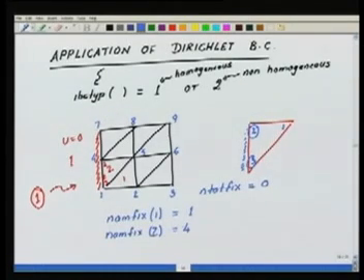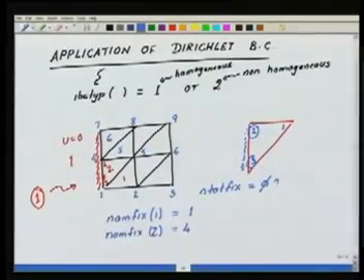Then I go to the other elements, and as I am assigning the degrees of freedom and the neighbors on the edges, I come to element 6. When I come to element 6, I find again that it is sitting on boundary segment 1, which has a boundary type 1, which means that here also the displacement conditions have to be satisfied. My counter would have become 2 at the end of the assembly of element 2.